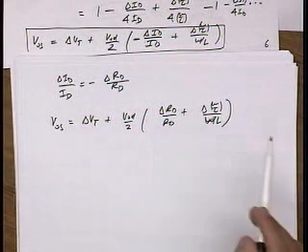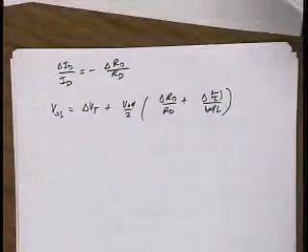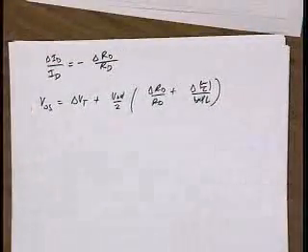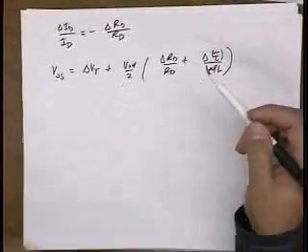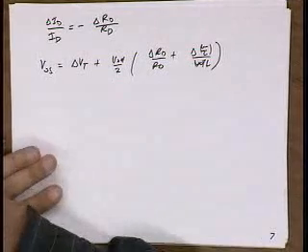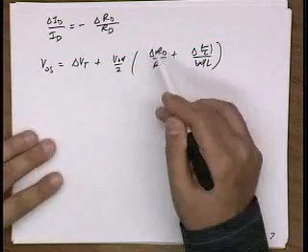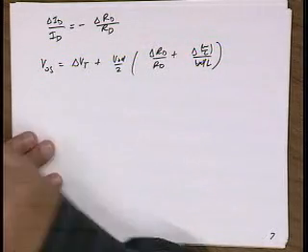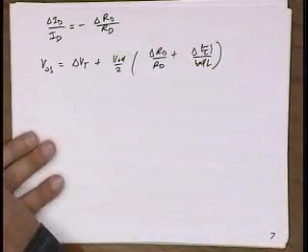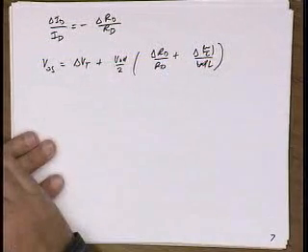Now this is pretty messy, right? By circuit analysis standards, we had to do a lot of messy calculations. You'll notice though that there's nothing magic about this. If I had to do this calculation over again and the amplifier were more complicated, instead of keeping all the offsets in one big equation, I would just take them one at a time, right? So I first assume RDs were not matched, and then I would calculate my offset voltage due to RD. Then I would assume W over L is not matched. Then I would assume my current sources are not matched. At the end of the day, they would just all sum up together like this. Okay?